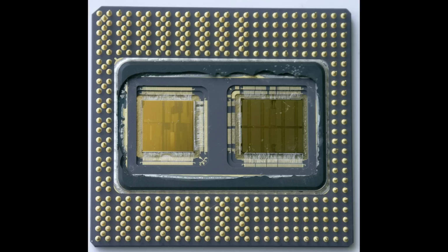And secondly, and this is the real killer, the way that those chips were designed, when they came out of manufacturing, you couldn't test either one until they were connected to each other. You couldn't test the memory without the CPU, and you couldn't test the CPU without the memory. And the only way to connect them to each other was to put them in that piece of ceramic. And by the time they're in the piece of ceramic together, you've reached the point of no return. If either chip is bad, you have to toss the whole thing. And so, especially early on, yields were bad.